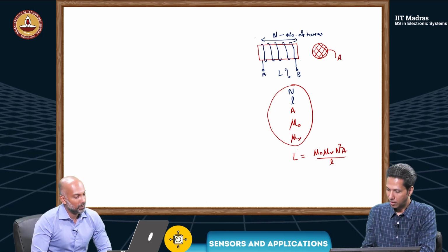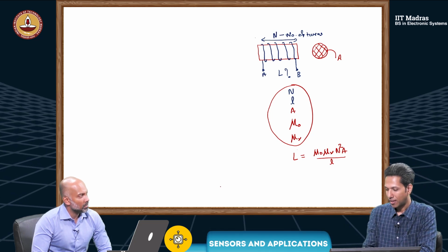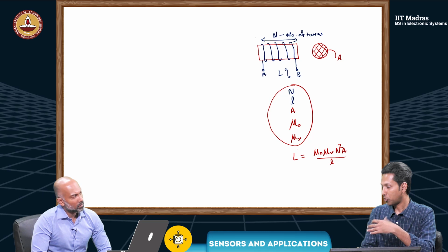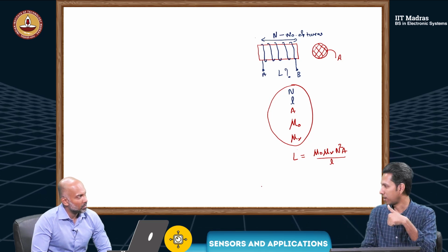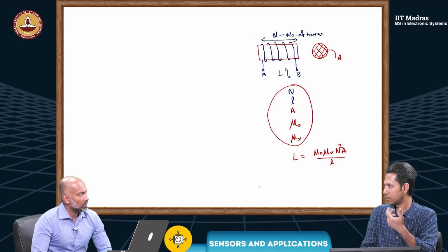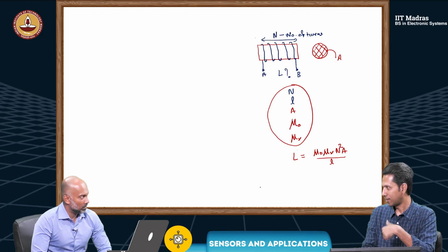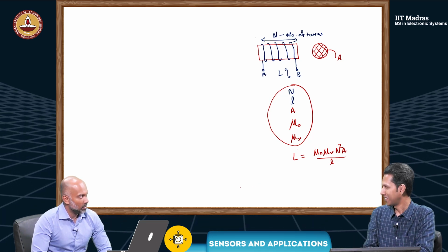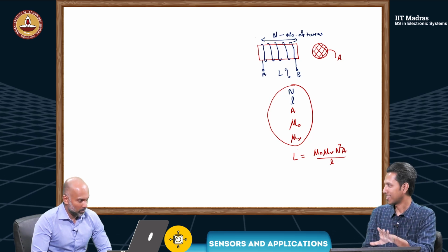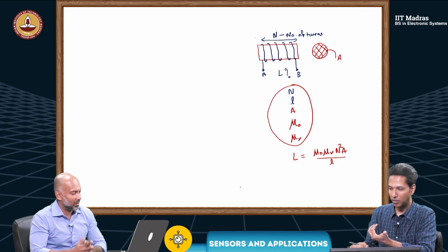The main parameters for inductance. And to measure this inductance, of course, the LCR meter will be applying some voltage, sending some current, finding out the impedance or reactance, and from there calculating the inductance. It's not a function of the current flowing through it, nor of the voltage that you applied. But to measure, you need some current to flow through it.